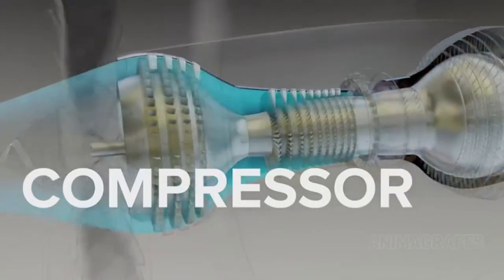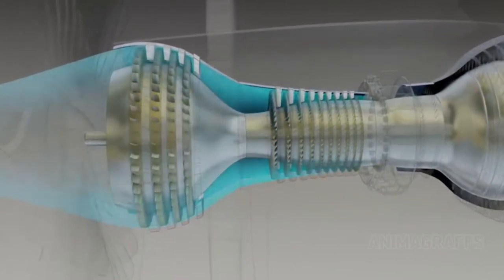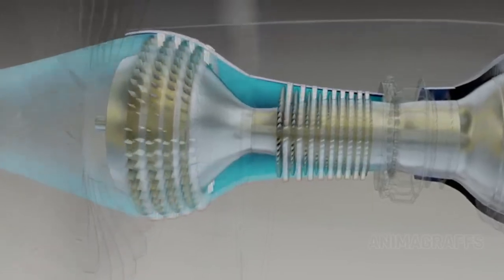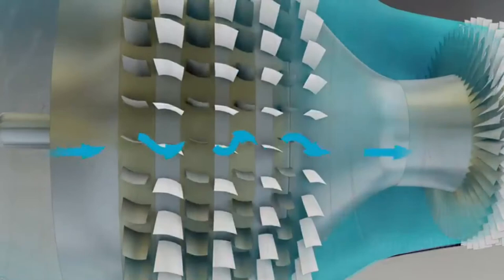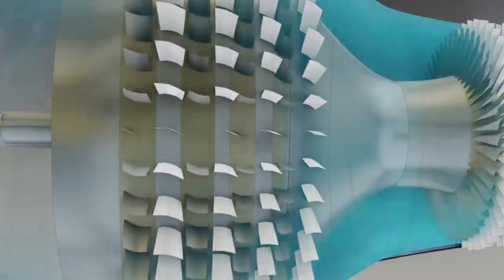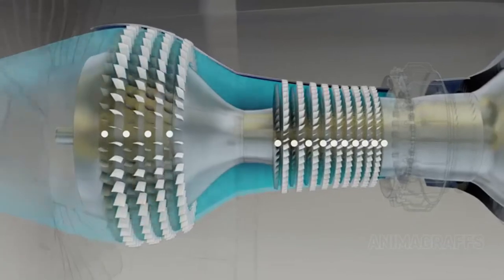The compressor. Compressed air makes for a much more powerful combustion reaction relative to engine size. Compression happens in stages that force incoming air into an increasingly narrow chamber. A single compressor stage is comprised of a spinning rotor paired with a ring of stationary stator vanes which are attached to the core casing. Rotor blades swirl the air as they force it through the compressor. Stator vanes slow this swirling momentum in exchange for increased air pressure. The compressor has 4 low pressure and 10 high pressure stages.